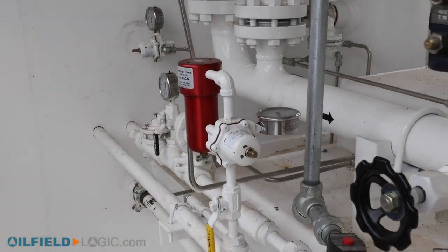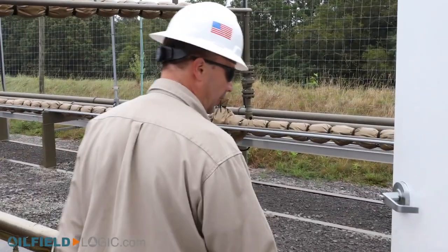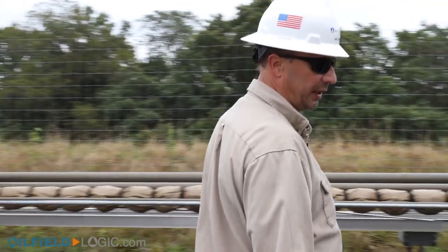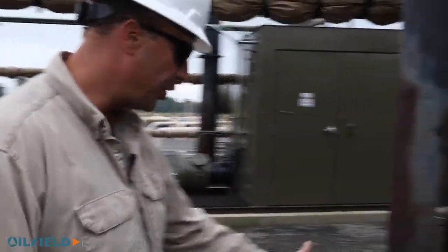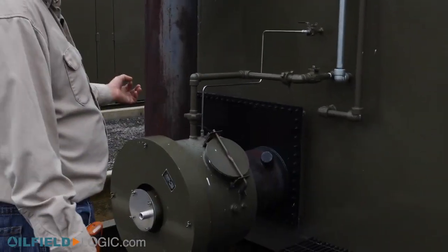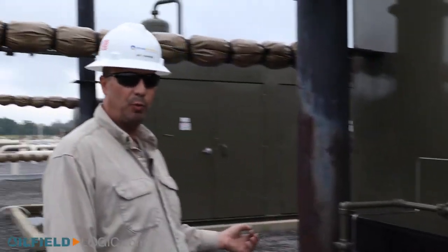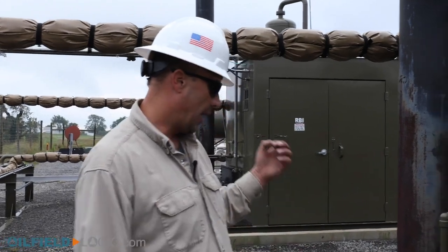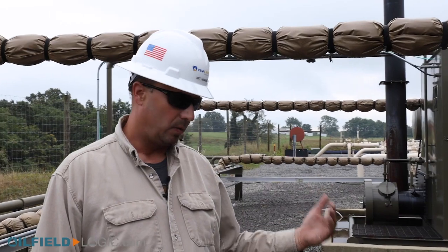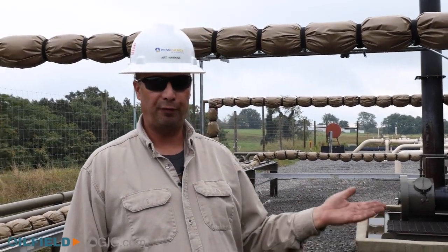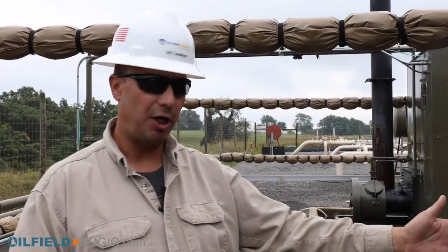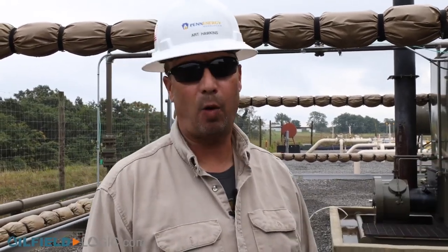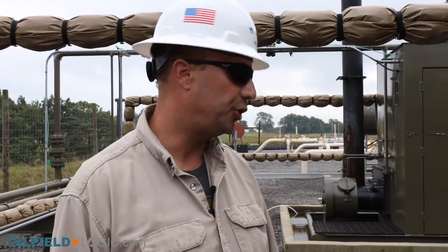We can walk around to the front side of our gas production unit and talk about how we keep heat in our water bath. This right here is our burn tube. There is a pilot that would be lit and burning all the time on this unit when we are operating. And by those thermostats, when we get below a certain parameter, when it needs fuel, it'll open up a fuel valve to allow gas to go to the pilot and light that burner to continue to heat up that water bath to our desired temperature.